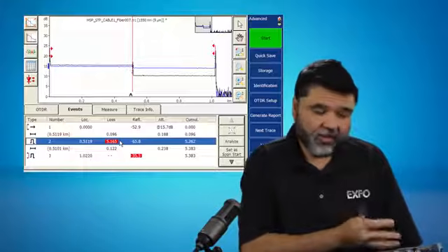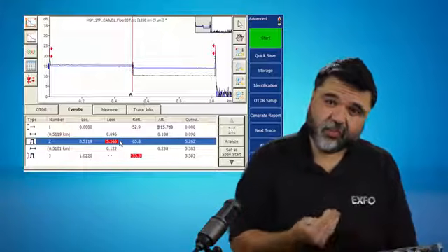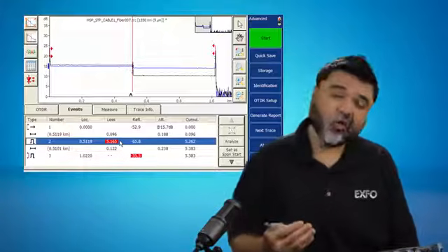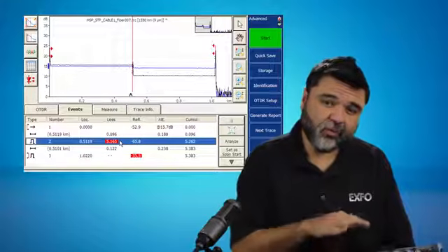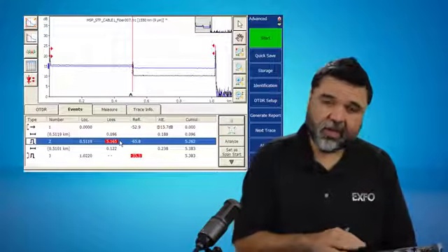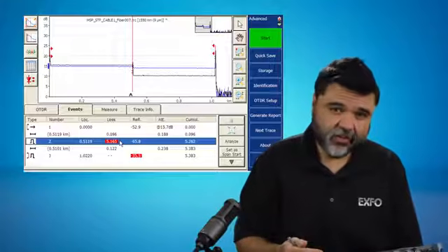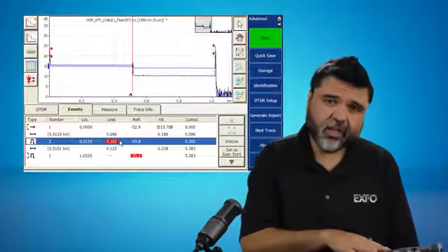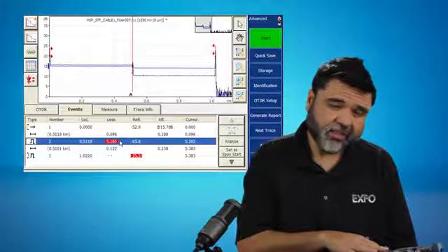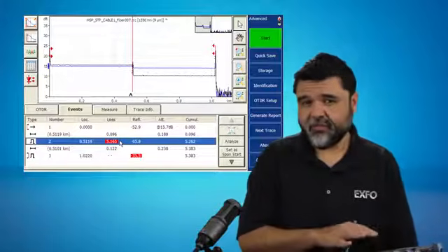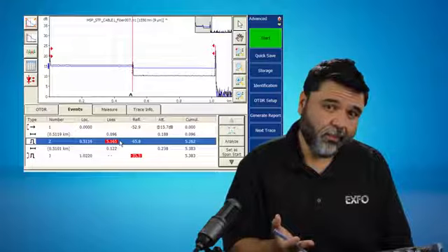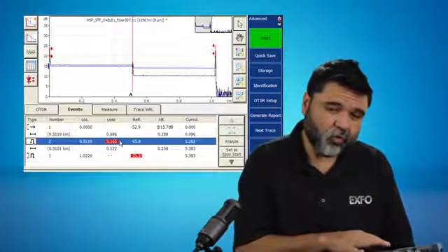So essentially I have an attenuator in the middle of my system for the longer wavelengths. The longer the wavelength, the more issues you're going to have with pinching or macro bends in the fiber. So if you're running L-band wavelengths up into the 1600 region, you're going to see even more loss at say 1625 or 1650. So it's important to understand what macro bending is and why you're testing both wavelengths.